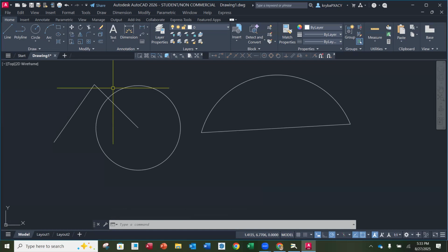Okay. And as you know, if I do something, there's a couple things I can do. This is another thing that I'm going to show you. If I want to delete this, AutoCAD's traditional way of inputting commands is to let AutoCAD know what you want to do and then do it. Sometimes we might, for instance, put a window around something, and you're going to notice you get these blue dots. These are called grips. And then you might hit the delete key on your keyboard.